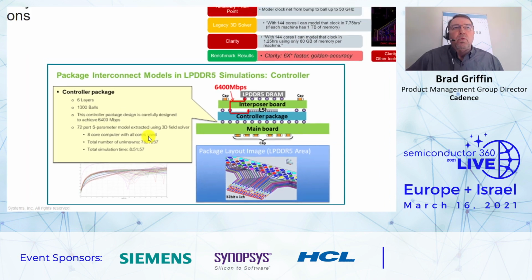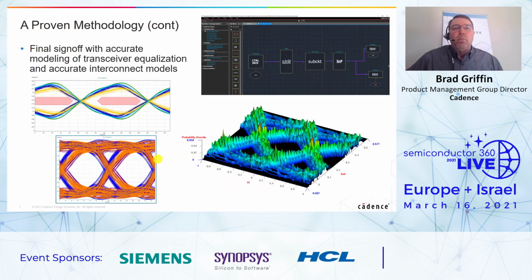So we want to encourage you to look at that as part of your proven methodology when it comes to DDR5. And so now you've extracted out the package. Certainly I would hope that internally you've got a reference design where you're going to put that package on a printed circuit board and communicate all the way to the actual memory module. So you want to be able to make sure internally you can look at that full system.